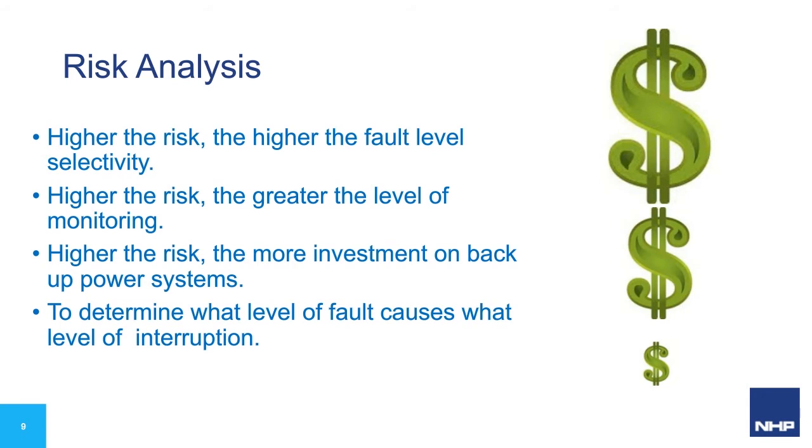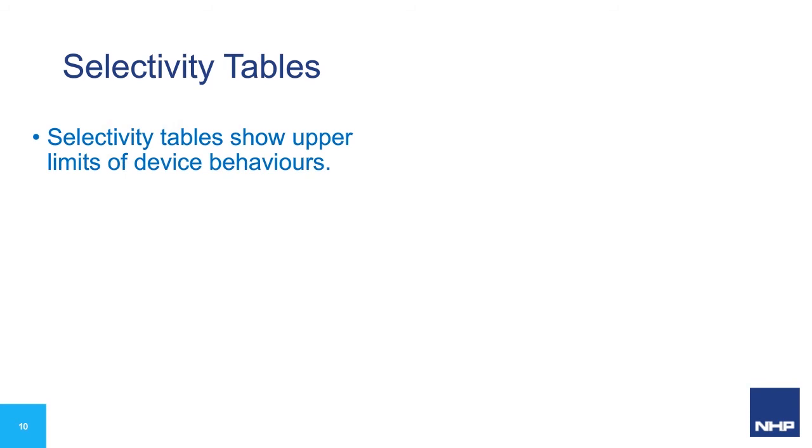There is a misunderstanding that by referring to manufacturers' selectivity and cascade tables, the chosen combinations of devices will automatically discriminate at all levels of fault. Now, this is not always the case.